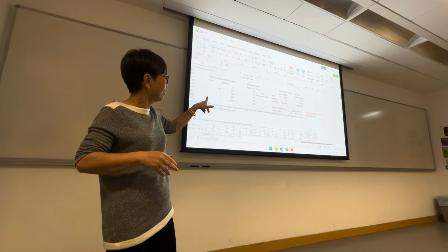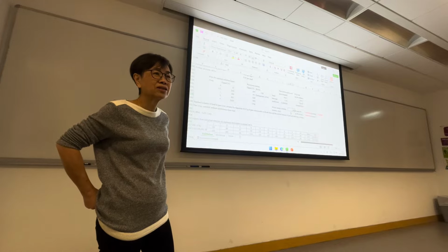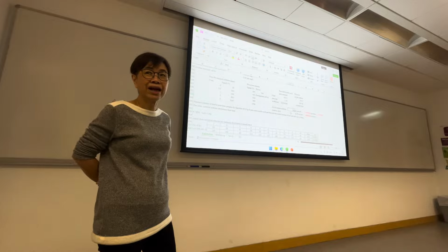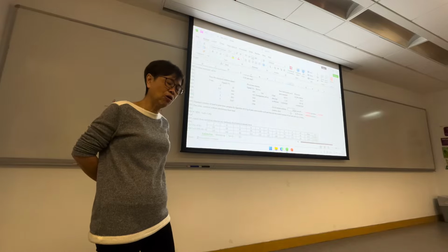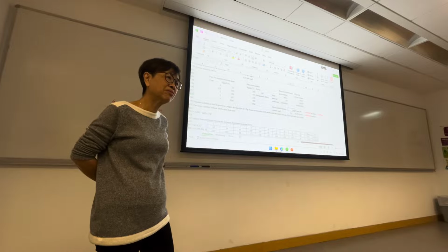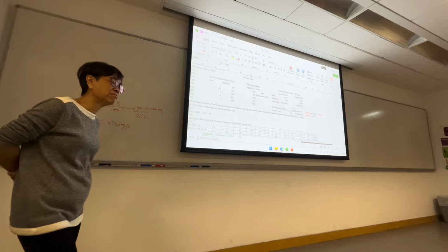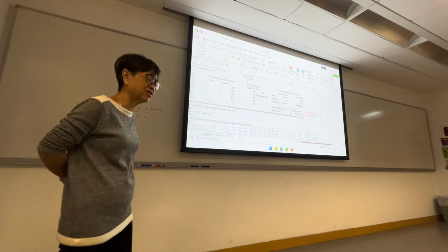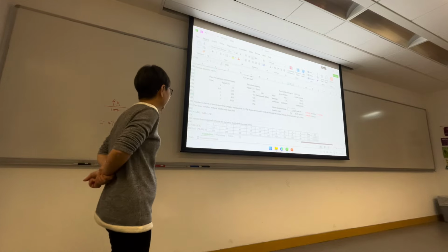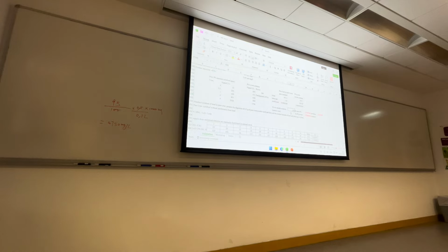So if the contribution of iron is very serious, affecting the result, then for different types of steel, you need to prepare different matrix calibration curves, okay? Because the amount of iron in different types of steel is quite different. So this is matrix calibration.